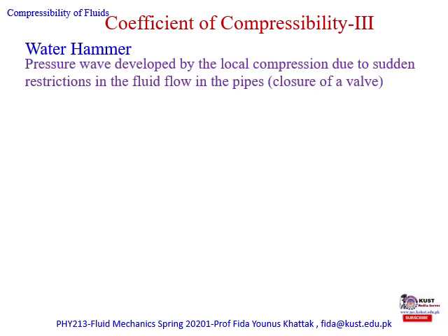It is caused by a local compression due to the sudden restriction in the fluid flow because of the closure of the valve, and a sort of shock waves are produced along the pipeline. These shock waves can have a very damaging effect on the pipeline and can potentially rupture the pipeline.